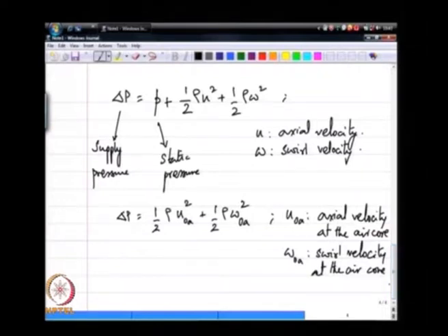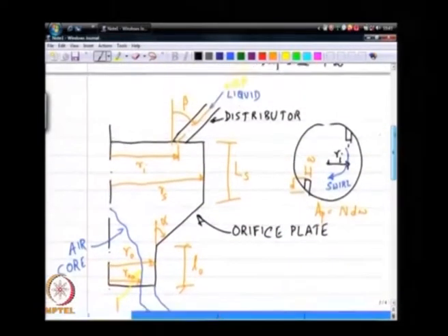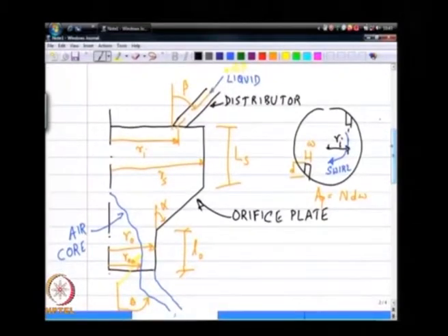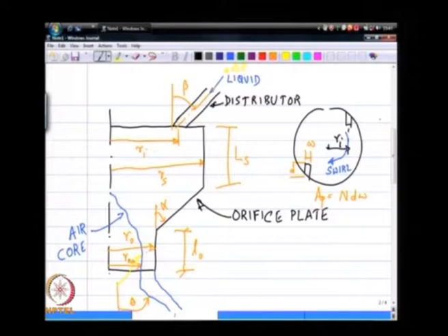I think at this point it is good to take a small detour down the lane of undergraduate fluid mechanics again. Remember, Bernoulli's equation is only applicable on a streamline. Now, if I take a streamline coming to this air core all the way extended into the tank, so, if I can draw a streamline going from this point here all the way into the tank, which is at some high elevated pressure delta P, we are applying this Bernoulli's equation on that streamline.